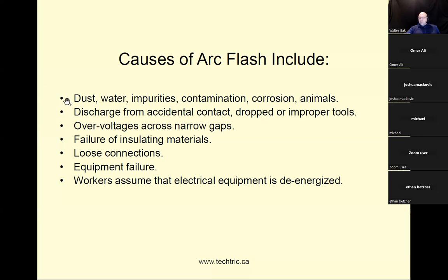And water. This is a tricky one here, because you're not going to pour water on an electrical panel on a regular basis. That's something we just don't do. However, when there's dust, there is moisture in the air, and some dust, for example sawdust, can accumulate some of the moisture, and that can create quite an interesting scenario. Because if there's enough moisture in the air, and if the dust retains enough water, it becomes conductive. Boom, here is your result.